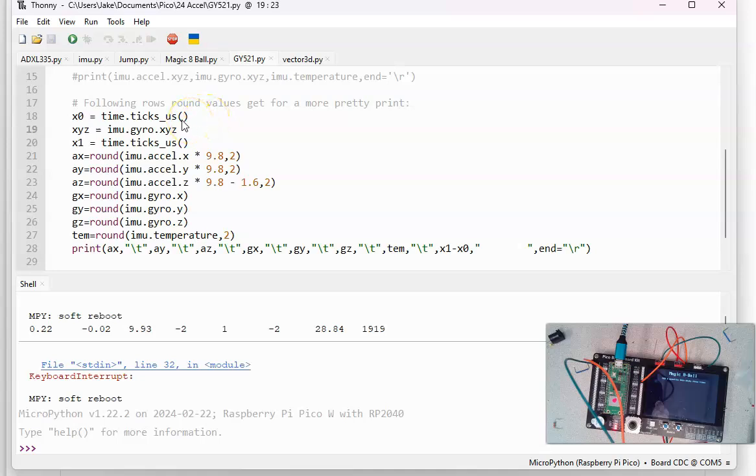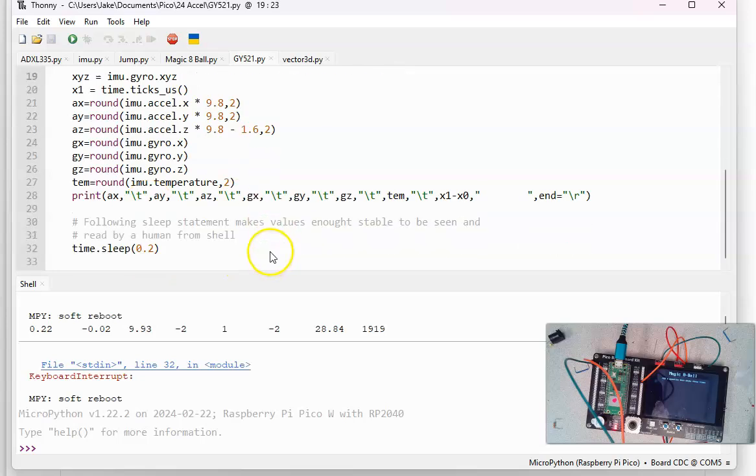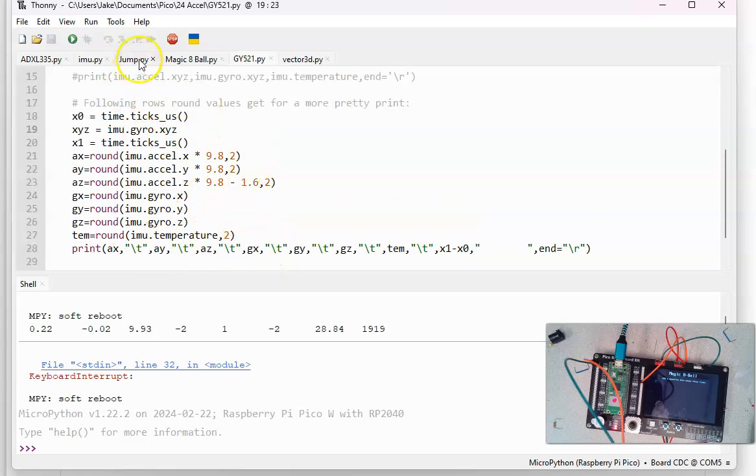Then read the gyro XYZ, read the acceleration X, Y, and Z. Scaled, it gives it in G's, point to convert to meters per second squared, times 9.8. Shifted, to get the DC term right. Also measures the accelerometer, or the rotational velocities, and then display them. So that's pretty much all you need to do to read it.